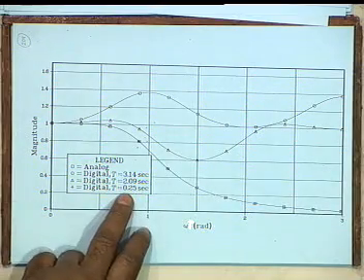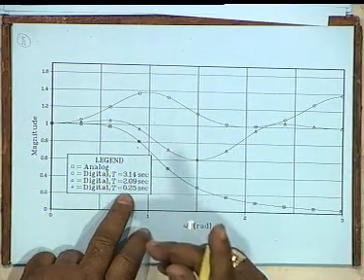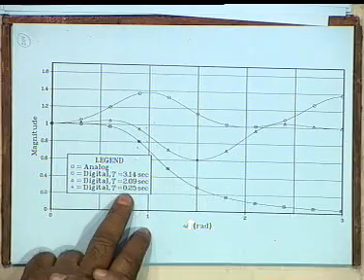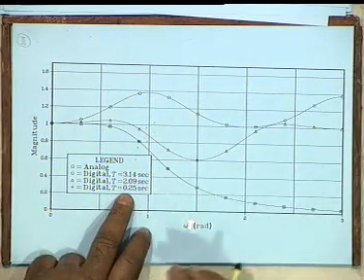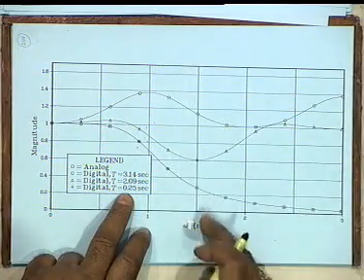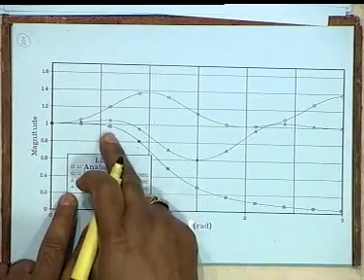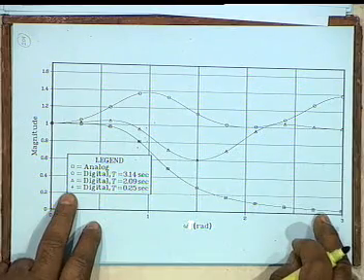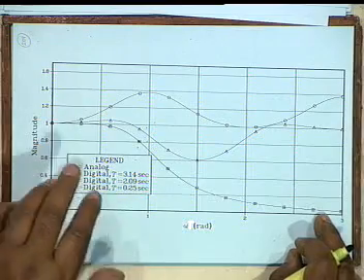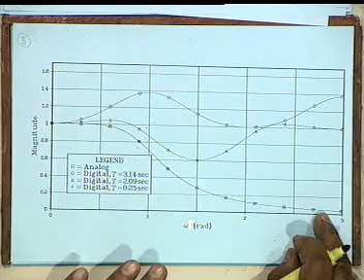4 hertz is not a practical value, because we took a normalized analog filter whose cutoff was at 1 radian per second, and therefore 4 hertz is a good enough frequency. 4 hertz, and you see the plus sign, that is, it's almost indistinguishable from the analog filter. Okay, you shall have to do this if you want to work with impulse invariant filter.